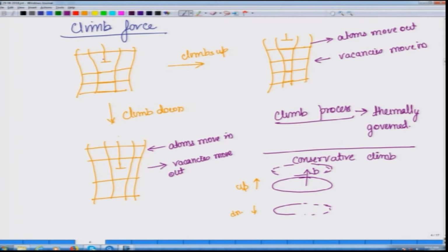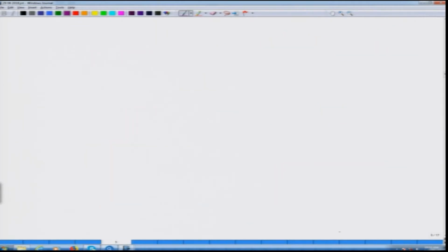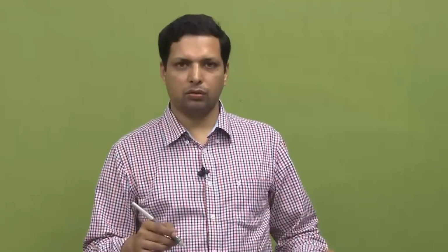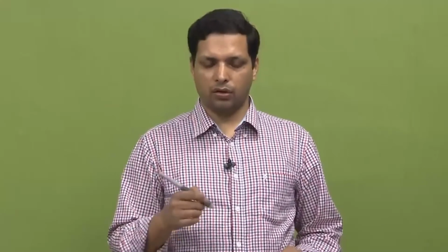Okay, so, coming to the approximate relation for this climb. Now, here what you have to first realize is that again you can have external stresses as well as internal stresses. So, you need thermal agitation, but also stresses can cause the dislocation to move, which will basically add additional stress for the dislocation to move, and this additional stress can be external or internal.